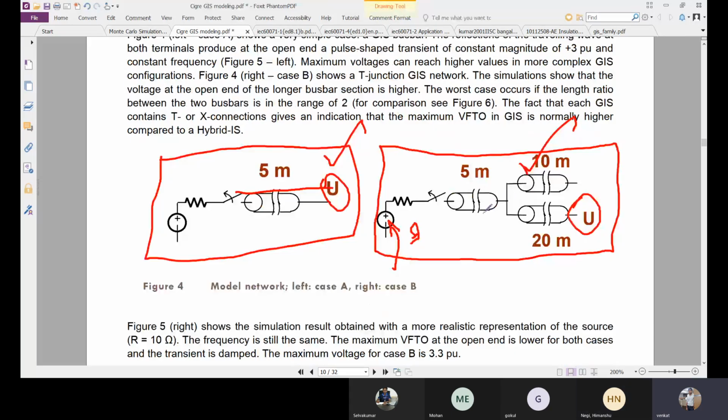So your voltage waveform will be getting more distorted, right? This distortion happens due to the meeting of different types of impedances on its way; the voltage will be getting more reflections and refractions. Here the voltage waveform will be in a uniform condition, right? Since it is not meeting any difference in impedance throughout its path, it will be in a uniform manner only.